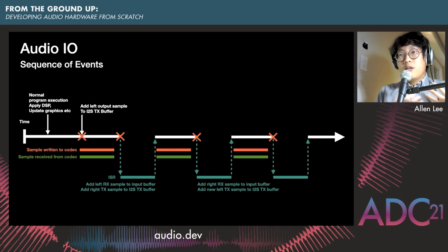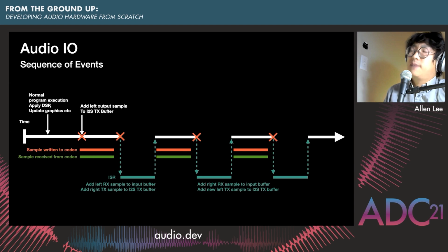The one interesting thing to note about this sequence is that there is a pretty high frequency of interrupts happening. If your I2S module was the only module generating interrupts, then that might actually be okay. But in Bitmaster's case, there's a lot of different things going on. Having this high frequency of interrupts might actually run the risk of starving other tasks from ever executing, things like the display and game updates, and also the audio processing.